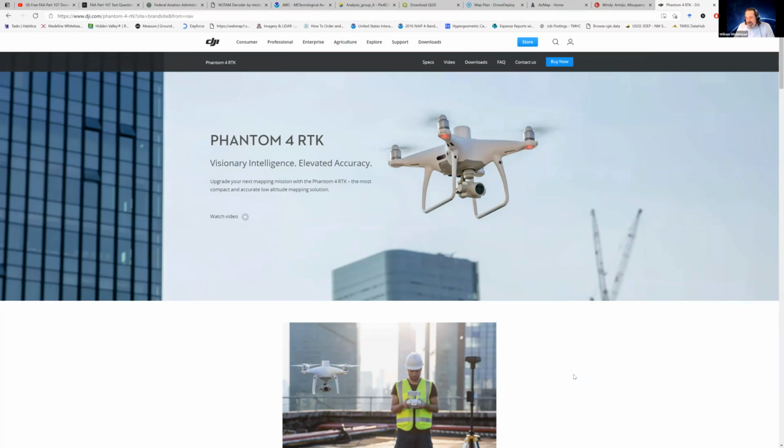file from, I believe NASA publishes that from the satellites. Because as we all know, in any GPS system there's a small amount of uncertainty if you're working live. You can reduce that down to almost nothing if you have a correction center that's constantly sending out what the correction is in its local area. That's what live differential correction should do for you.